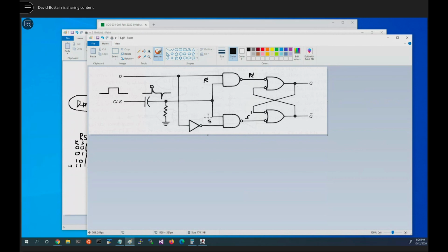Now I may have labeled it backwards. These could be set and those could be reset. It also, because this is a NAND function, may be creating the signal by virtue of it dropping as opposed to by virtue of it rising. But we know that from looking at the latches on a different day. So here we have our differentiator. The pieces of this that we would care about are that this part out here is a simple latch. Almost all flip-flops and latches will have this somewhere in the picture.